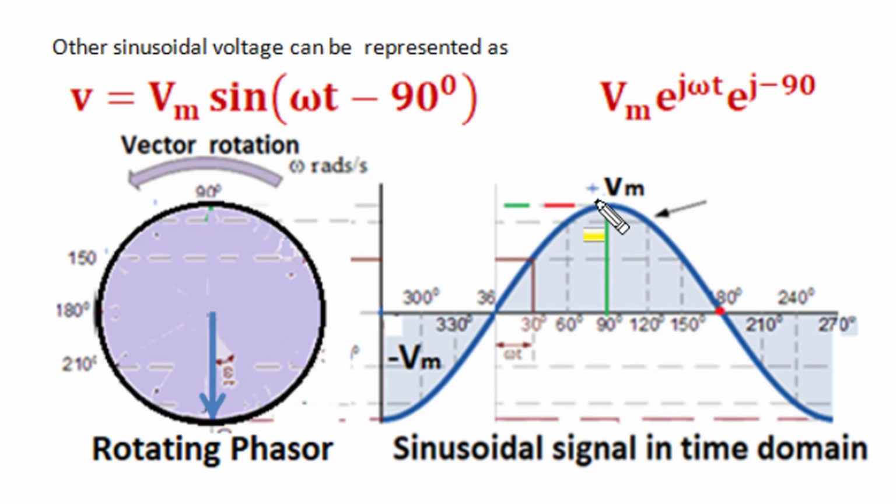Similarly, when a sinusoidal voltage starts with negative peak instantaneous magnitude at t equal to 0, then its phase angle is treated as minus 90 degree, and its exponential phasor representation shows the phase as minus 90 degree. Here we'll draw a phasor of scaled length peak magnitude Vm, and its initial t equal to 0 position with the horizontal reference is minus 90 degree. Minus means it is in clockwise direction, and it makes a clockwise 90 degree angular position as shown here, and its projection on the vertical axis represents the t equal to 0 initial value.